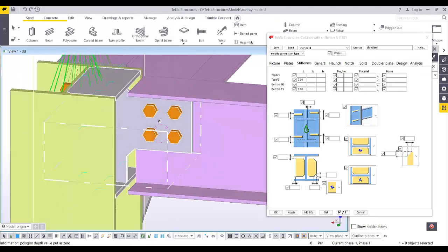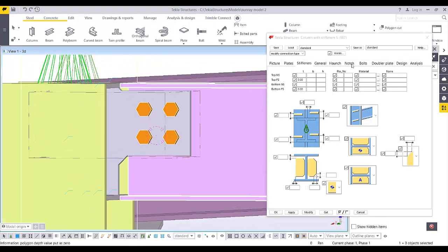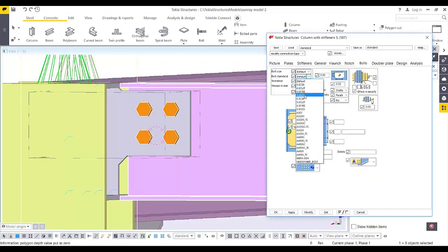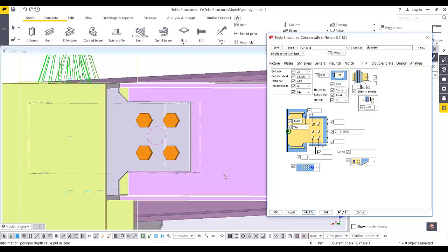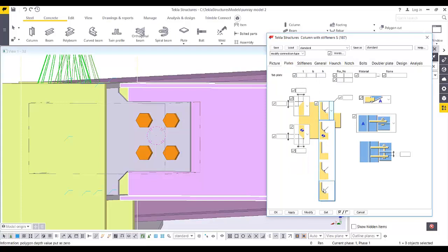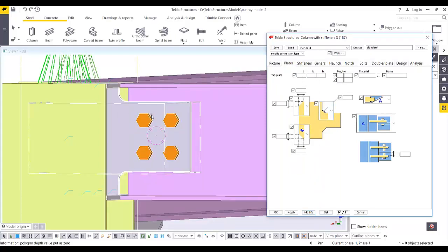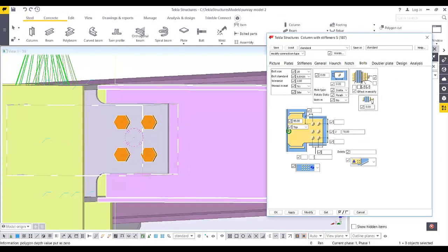Okay, so this one, I think 4 bolts is okay, but I just need to set up properly, so I can select the 20 size of bolt, and then here the first down hole could be let's say 80, and then 2 into 70, modify, yeah, and then for the plates I will just use the round one, okay, and then for the pitch here I'll just use also the 70, and then this one is 40, 40, 40, and then 40, and then modify.